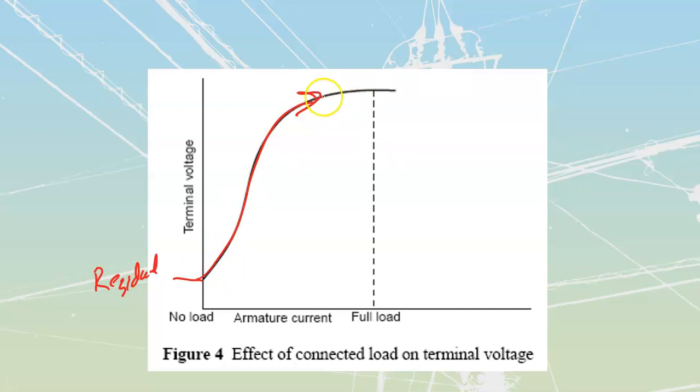It's going to come up, and then we start to hit this point where any increase in the amount of current going out is no longer going to give us any more useful flux. We start to hit that point of saturation. Once again, you should be able to start to see that hysteresis curve coming out of this. We see these rises in voltage and current give us a rise in magnetism, but then the magnetism starts to saturate.